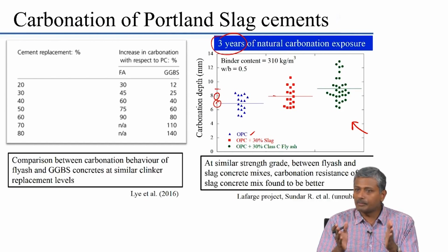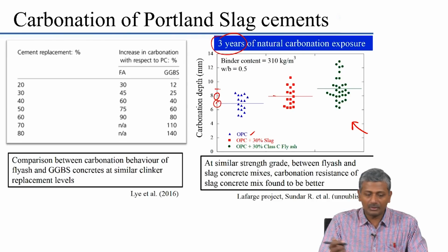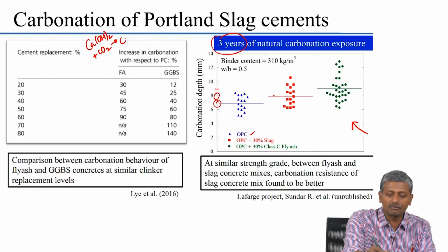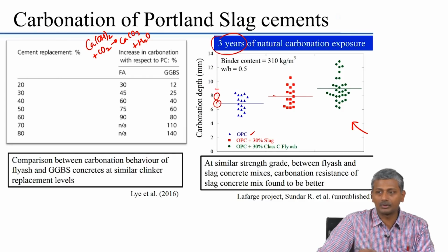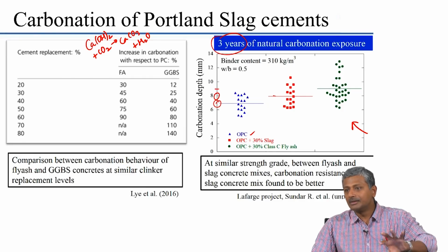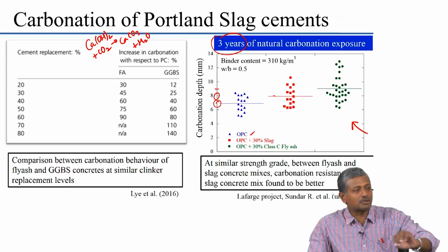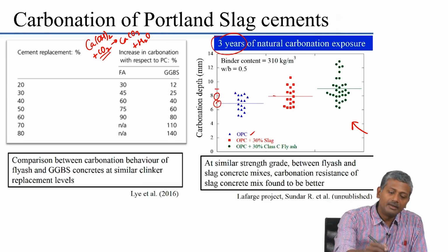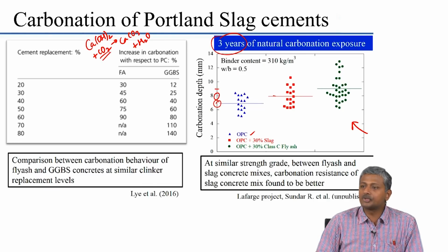Okay. What does carbonation do? It consumes lime, right? You have calcium hydroxide plus carbon dioxide, that leads to formation of calcium carbonate, and of course, there is a water molecule that goes out in this reaction, but then again this is not indicative of the actual process that takes place. We will discuss that later. Some moisture is actually needed to convert this carbon dioxide into carbonic acid that actually consumes the lime.